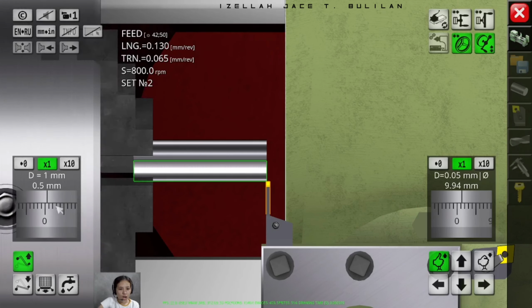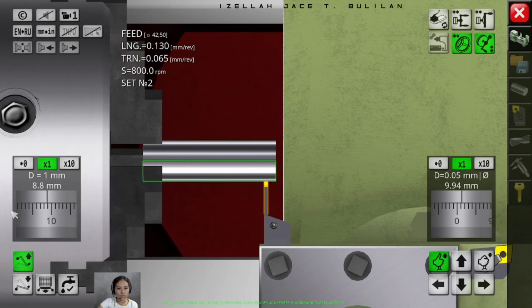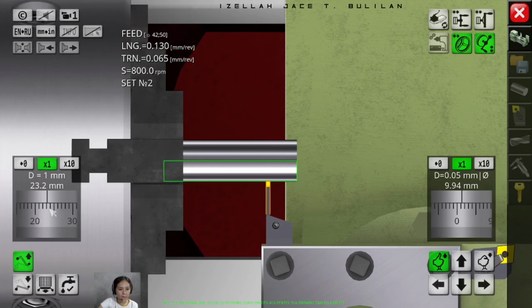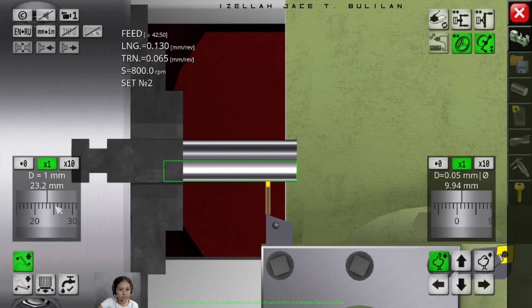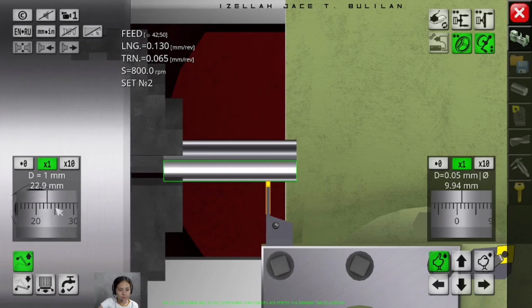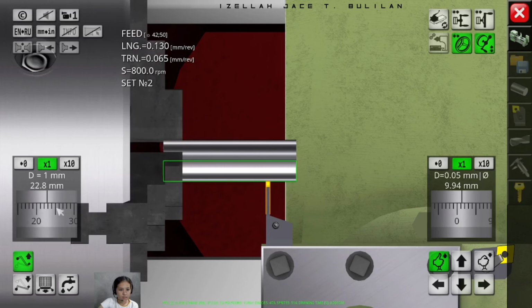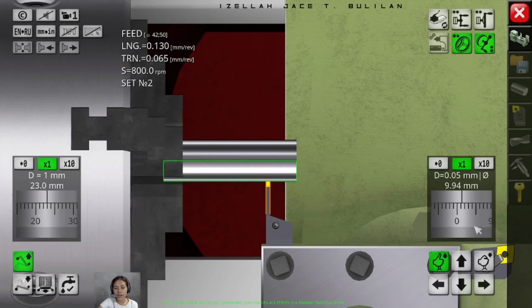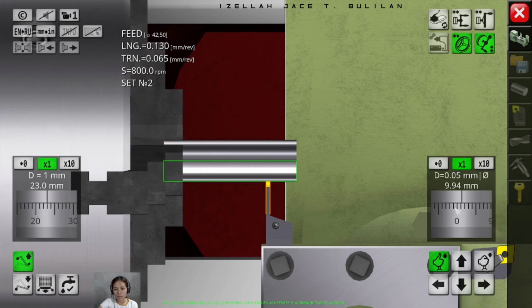And I'm going to start the first operation that we're going to do, which is the undercut, moving our cutting tool number 43 to 23 millimeter in length. Okay, and we're going to move our transversal movement up to 18 millimeters.